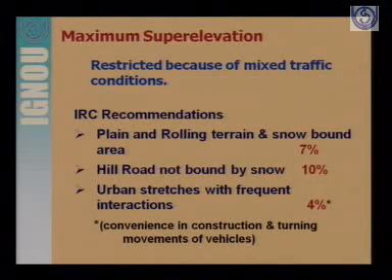Now, when the road is open for mixed use, there may be a problem for vehicles moving at a slow speed. They will feel the problem. So for roads designed for mixed traffic, the Indian Roads Congress recommends maximum super elevation limits, as mentioned in the IRC codes.